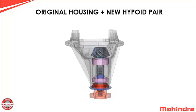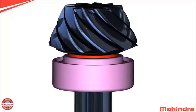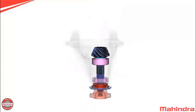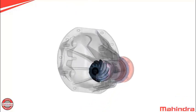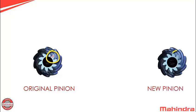In the first situation, that is original housing plus new pinion, we need to note down the thickness of the existing shim pack. Check and note the Z value etched on the old pinion top surface. Also note down the same Z value etched on the new pinion.